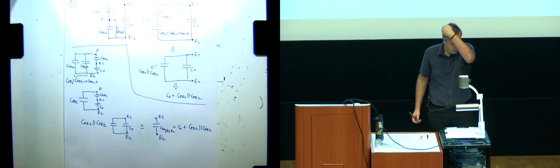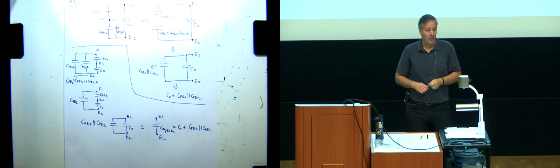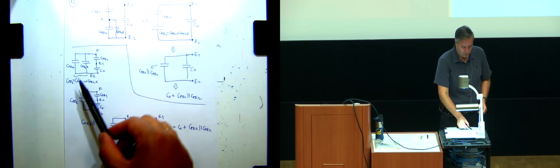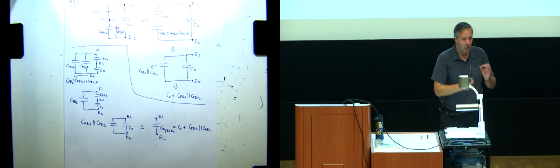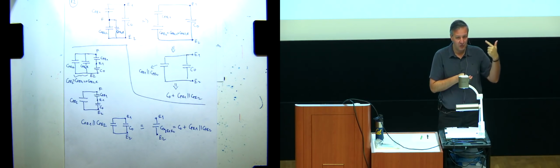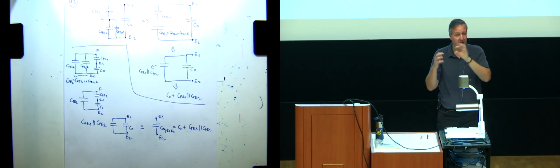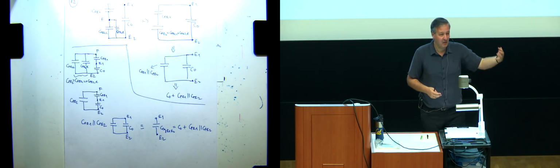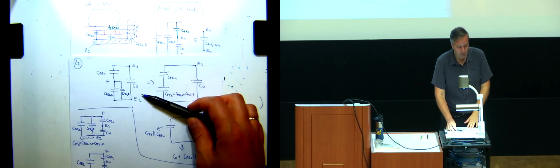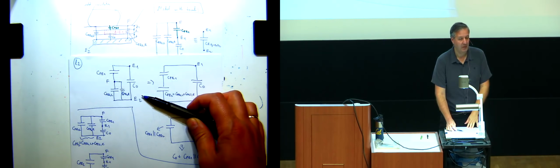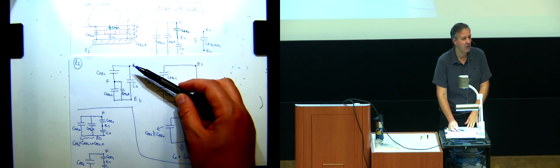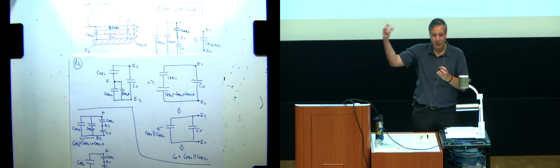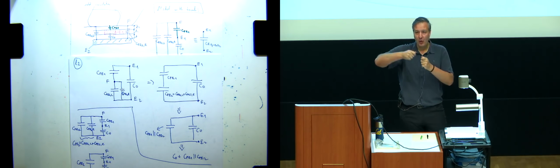Right. So, essentially, you can go either way. Either try to see in your existing circuit what are the smallest patterns, subblocks that you recognize, and start simplifying from there. And then hopefully things will become clearer. So it's a kind of cascaded equivalence. Or try to redraw your circuit so it is more clear. But when you're redrawing, just make sure that it's like a graph. Your vertices are your nodes, and your elements are the branches in the graph. And make sure that you always obey.